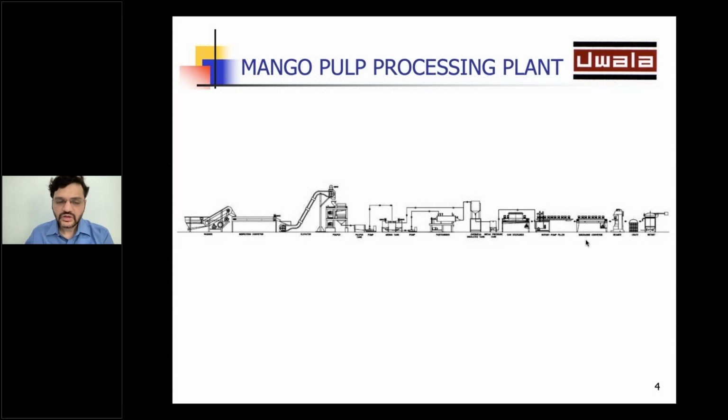I had talked about aseptic filling as a common way of processing as well. Now, aseptic filling is used in plants where the capacities are 5 tons per hour or more. For plants of less than 5 tons per hour, we normally use canning. So wherever the plant capacity is 5 tons per hour or more, we use the aseptic filler. In the aseptic filler, again, the first few processes are the same. So up to the pasteurization, the process is the same.